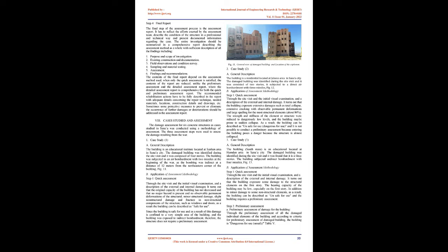A residual capacity ratio index R, which corresponds to building damage, is defined as the ratio of capacity of post-damaged to that of pre-damaged condition, i.e., the ratio of the residual capacity to the original. Table 4. Residual capacity ratio index, R, according to damage severity.